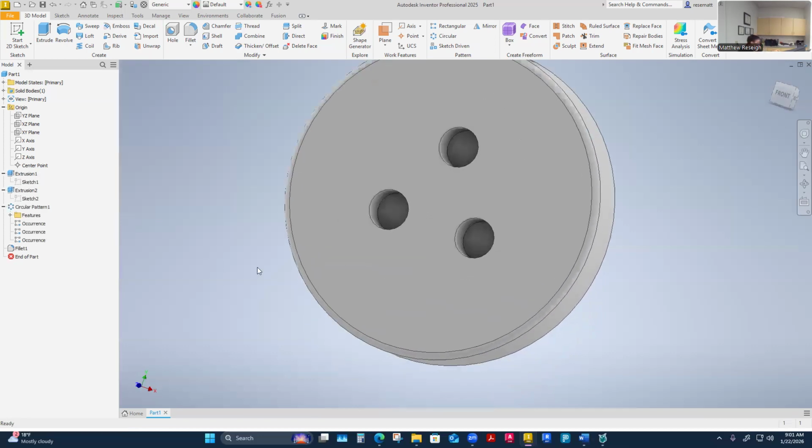That's what I usually avoid by doing through all anyway. This is the reason why I am typically a through all person, unless there's a good reason not to. Because that would have already accepted the half inch change, and it wouldn't have made me have to go in and do a dimensional change on the extrusion for the hole. And really, if I would have included that sketch in the original sketch and never extruded that part of the hole separately, I wouldn't even have another sketch and another extrusion to deal with. But because I made them in 2 different sketches, I do have another sketch that I have to deal with and that extrusion.